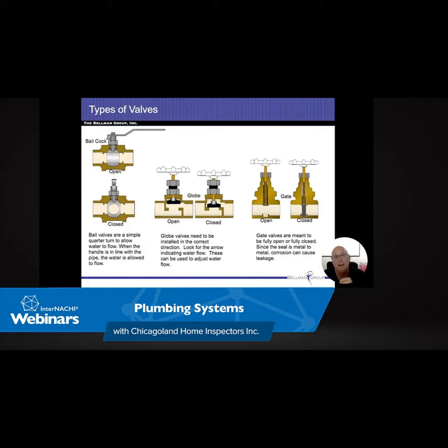This is a pressure relief valve we found in a house. We did not hook this up this way. If you look at the arrow on there, it's actually pointing towards the tank. So somebody had to do some configuring to make this happen. They had to put in a nipple in order to get a male thread into the tank and then put the female to thread into the exhaust of the pressure relief valve. And then they went ahead and put another female fitting on the bottom end.